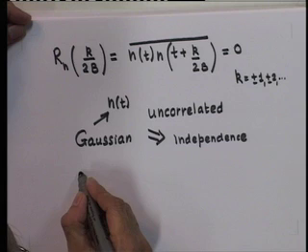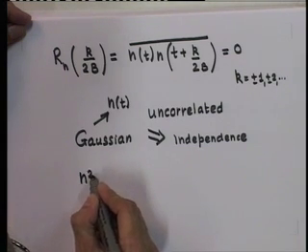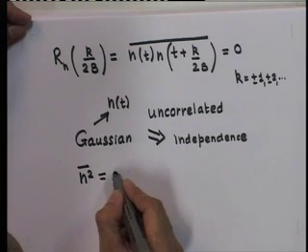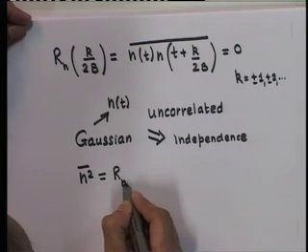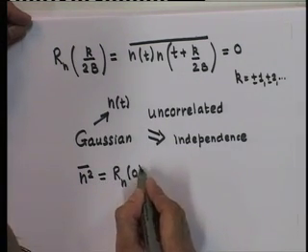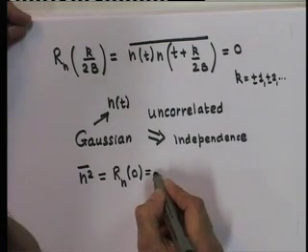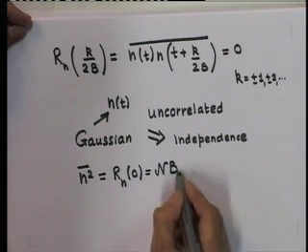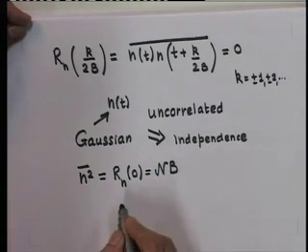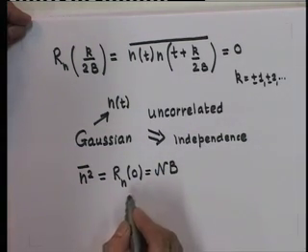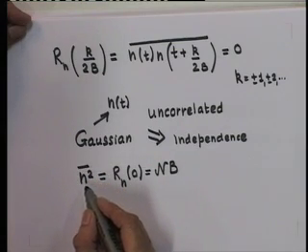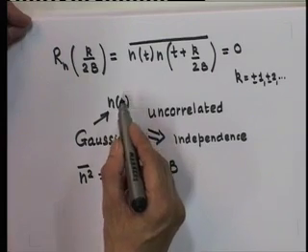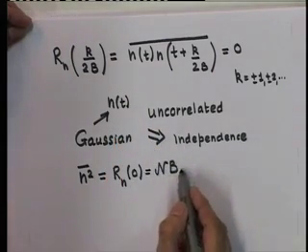Now, the variance of the noise samples, which is equal to autocorrelation evaluated at 0 lag, is equal to n times the bandwidth of the noise process, that is B. Hence, the variance of each Nyquist sample of n(t) is nB.